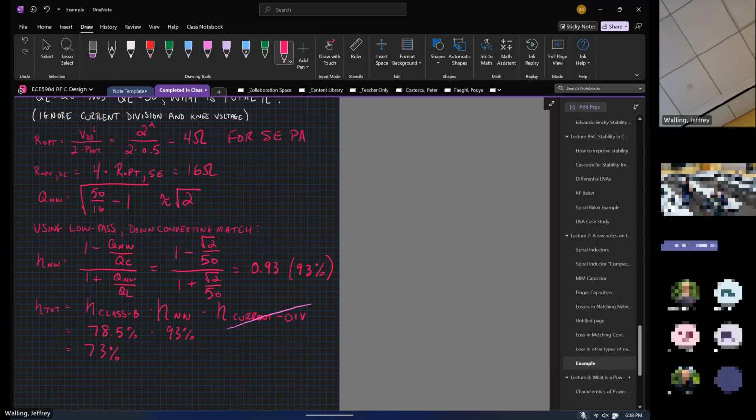We tend not to cascade a lot of matching networks together. Most of the time, the most number of components that you're going to see on an RFIC, unless somebody's trying to make an absurdly wideband amplifier, they might do something. There are things called distributed amplifiers, where they're cascading transmission line sections and trying to make a synthetic transmission line. Unless you're trying to do something like that, you're typically going to see 3, maybe 4 elements, usually 1 spiral and a couple of capacitors. There are exceptions to that rule, but that's mostly what you're going to see.